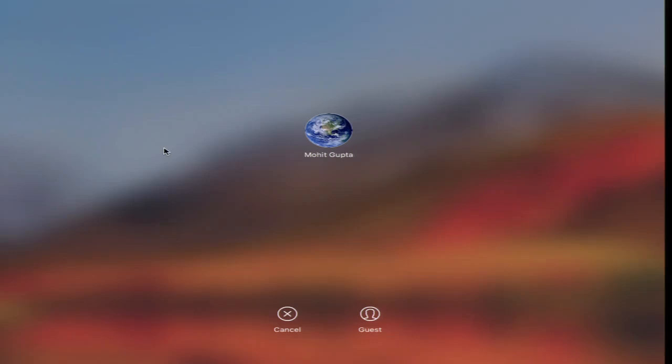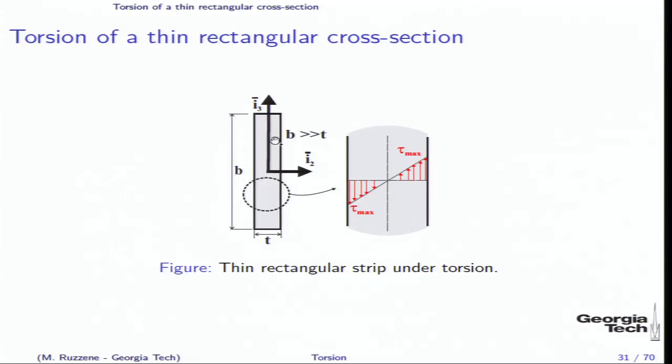So now you can see that in our shear stress expression which we obtained, tau 13 is in a linear variation with x2. If you go from minus t over 2 to t over 2 in the cross section, there is a linear variation similar to what you saw in the circular cross sections, and this variation is governed by this expression.